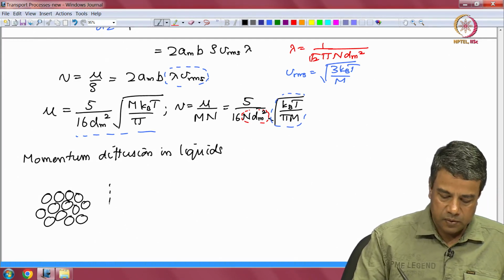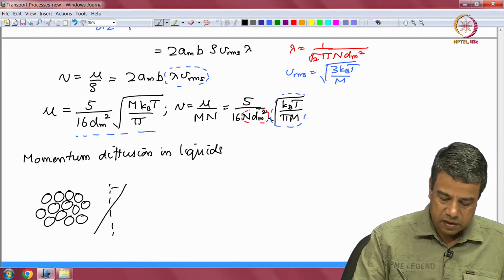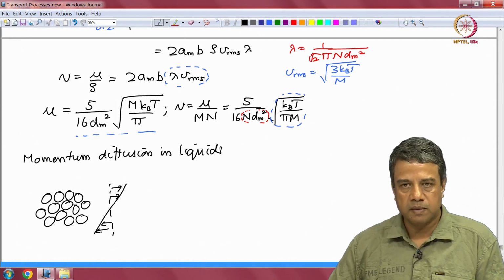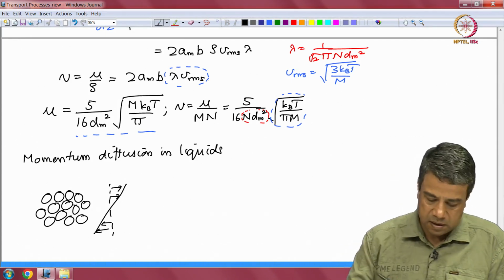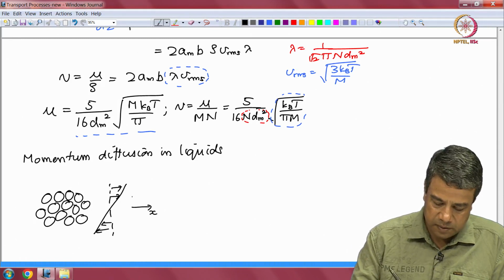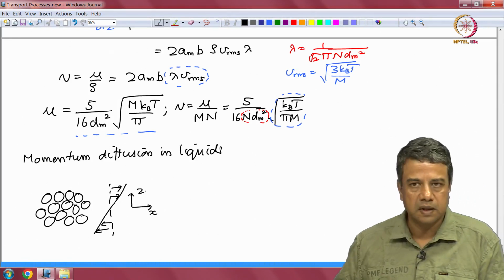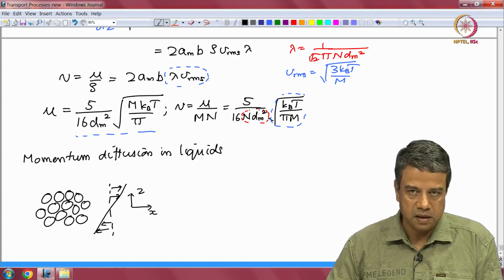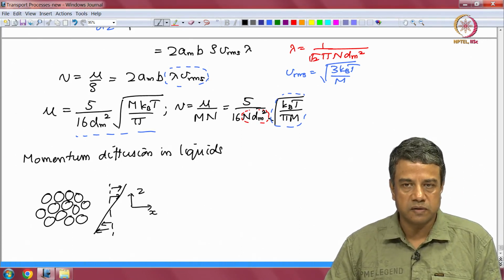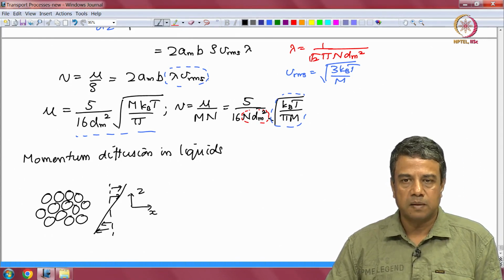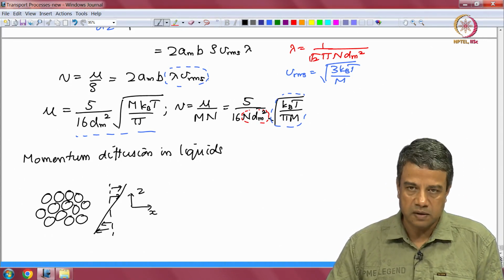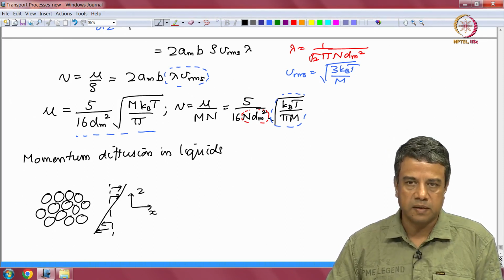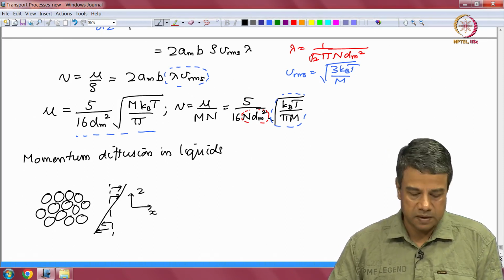However, if I impose a velocity variation, momentum transport of the, in this case, the x momentum in the z direction, does not require physical motion of molecules. Momentum can be transported due to intermolecular interactions. In the case of hard spheres, this will be discrete collisions between molecules.